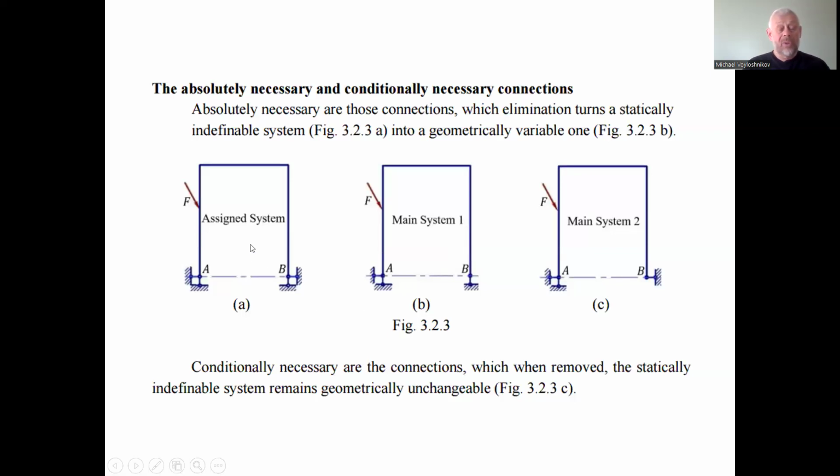And first of all, to use the force method to determine the forces and supporting actions and the forces inside this frame, we first have to make the main system of this frame. For the main system, in this case, we can speak about 2 options. We can remove one link, this one supporting link or another one. So each of the 4 links we could remove.